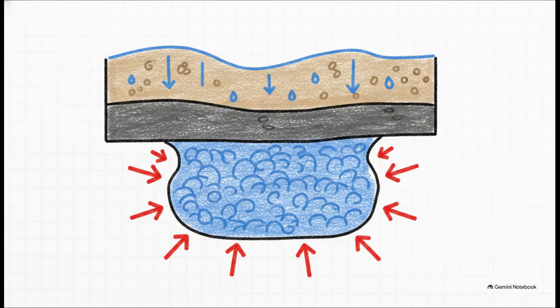If we zoom out from that microscopic maze, this permeability creates massive underground water systems that we call aquifers. We broadly classify these into two types. First, you've got an unconfined aquifer, which is essentially just a free-flowing zone where the upper surface is the regular groundwater table. But then we have confined or artesian aquifers. This is where water is physically entrapped under pressure between incredibly dense, impermeable layers of earth. Engineers measure the potential of these massive underground reservoirs using the coefficient of transmissibility, which is basically a calculation of the rate of water flowing through a full vertical strip of the aquifer.